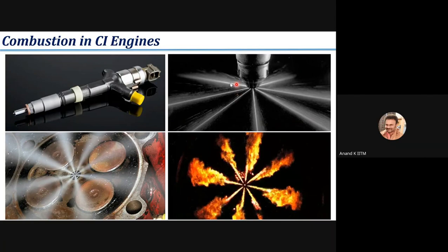So once the liquid phase fuel gets into gas phase, it has to mix with the surrounding air in the required ignitable proportion. So mixing has to happen. Then once the mixture reaches the ignitable proportion, and if there is an ignition temperature available nearby, then the radical formation will start to take place. Once the radical formation starts, ignition happens.